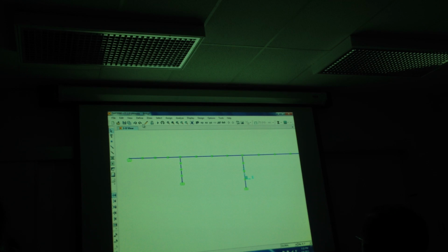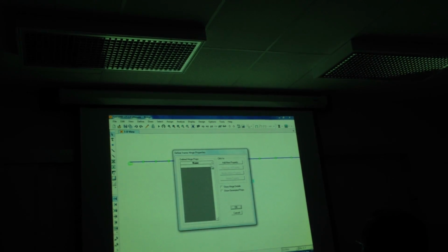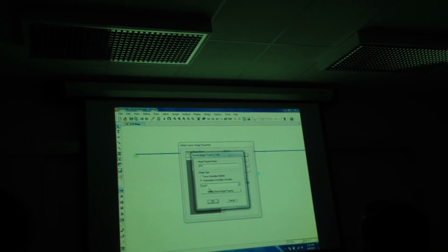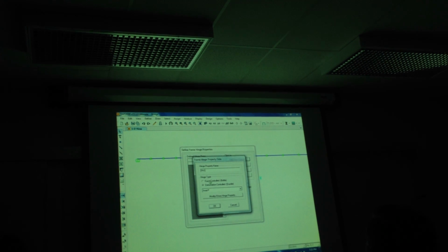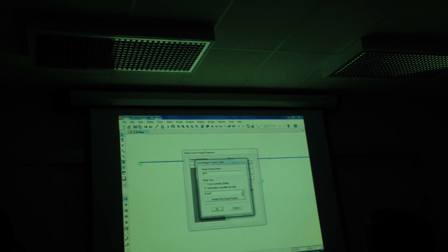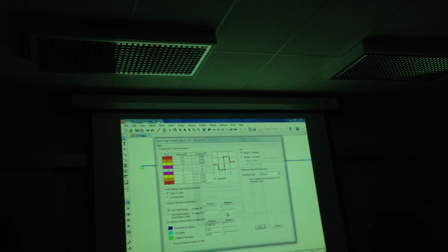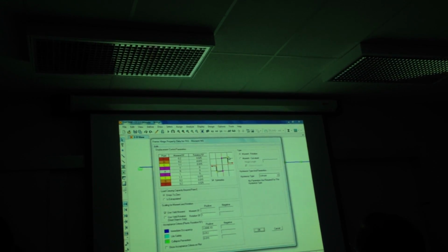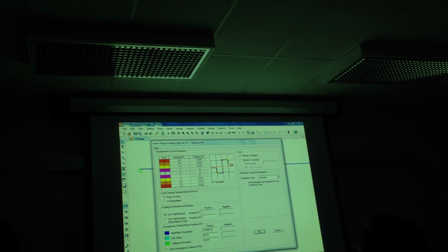We need to define a plastic hinge, so let's say define section properties, go down to hinges, and then add a new property. It says concrete. Okay. I'm going to call it PH, plastic hinge 1. Deformation control: I don't want it to be an axial nonlinear behavior, a squishing like this. I want it to be moment rotation. So you click here, you change it. It could be any of these types of nonlinear behaviors, but ours is moment 3 that I'm interested in. So this pops up and it gives you what the moment versus rotation can look like at the plastic hinge. It's rigid, which is correct until the plastic hinge forms, and then it takes on these other values.